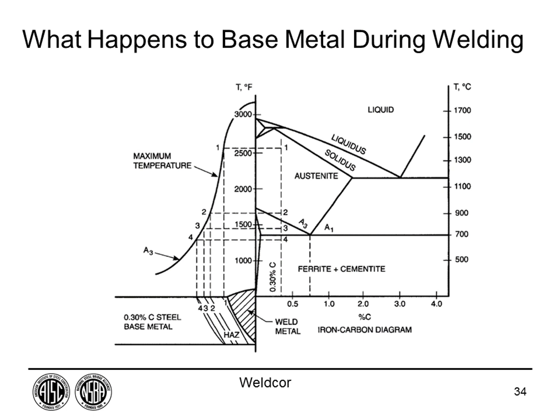But also what's critical is this area right here, the heat affected zone, because it starts out in the austenitic range. If it cools too quickly, what will form is martensite. So we want to control the hardening of this area right next to the weld. As we move further away, we get areas that are not heated to such a high temperature, so we'll have slightly different structures of the material. We call this area the heat affected zone, abbreviated as HAZ.